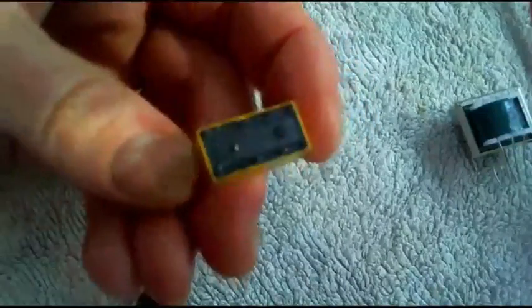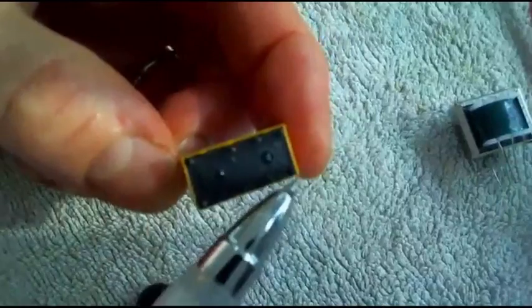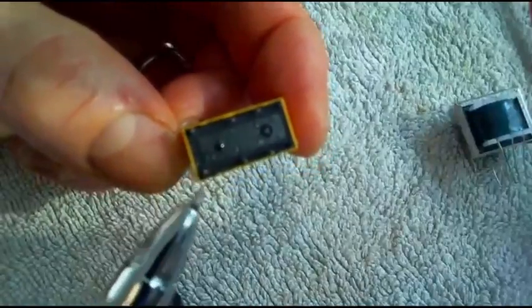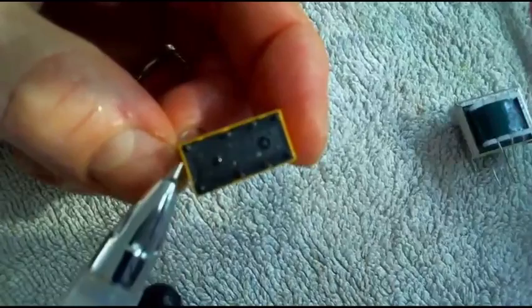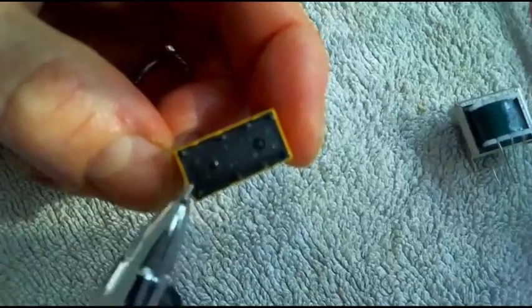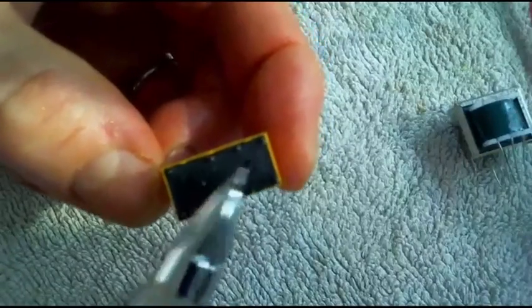And last but not least is a switch. This is a relay. And if you were to look up this number and find a data sheet, you would find that on the back side you have some leads. These are not showing up so well in the camera. You have 8 leads, and 3 are spaced more closely. Leads 1, and I believe it's labeled 16 over here, actually have a coil. They have an inductor between them, and that's providing magnetization for a switching mechanism.